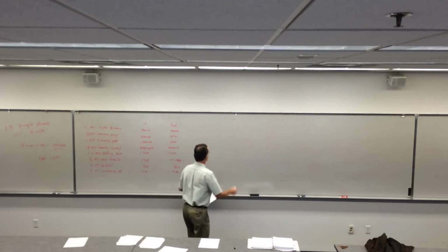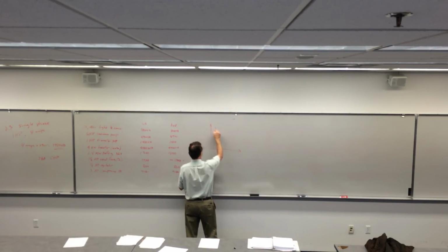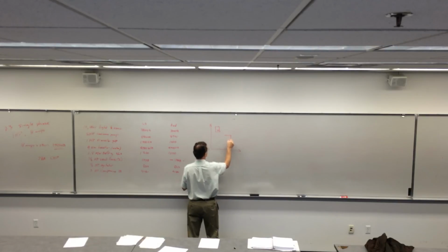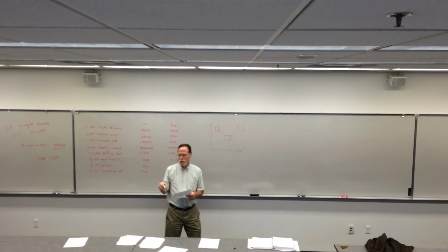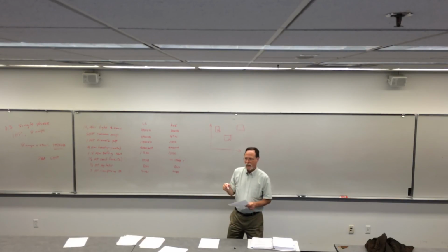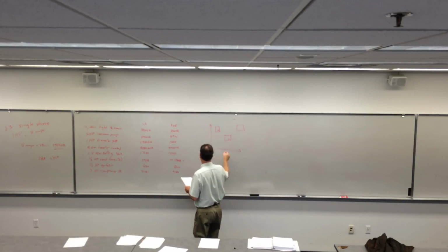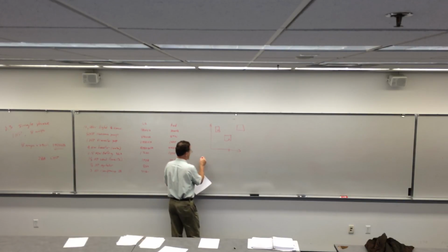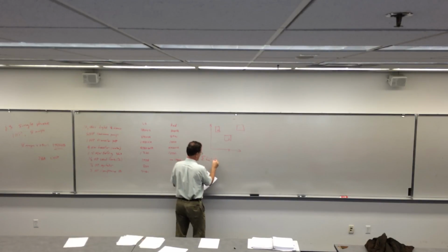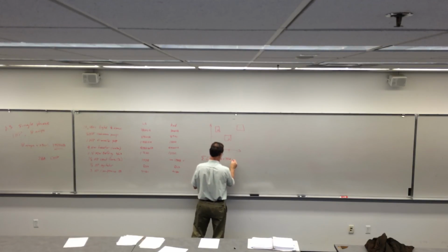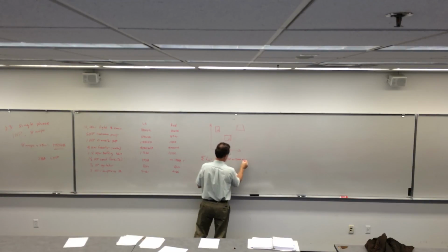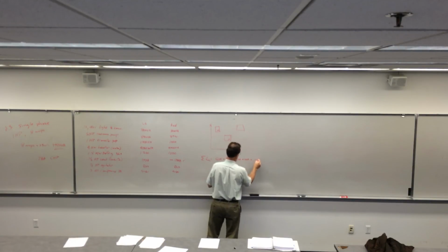Problem 3 was the one with the buildings everywhere. It had the little X where it was, and all this kind of stuff. Most of us got that. I had a couple that were curiously way off. All I can think of is we just missed a dimension. The sum of the loads was equal to 50 amps for one building, plus 75 amps for the other, plus 120 amps, plus 160 amps, plus 15 amps. So you end up with 420 amps of the sum of the loads.